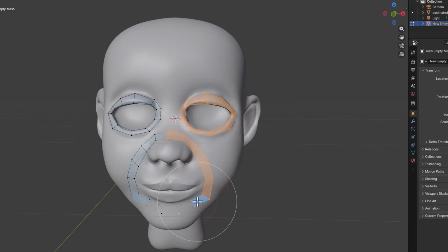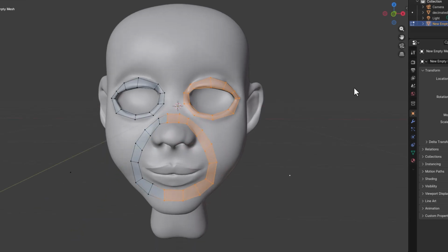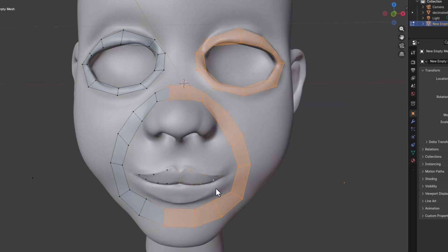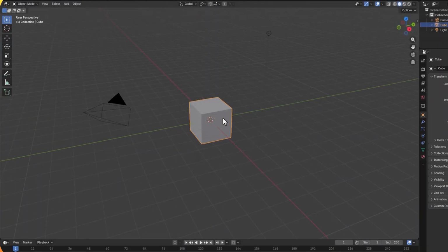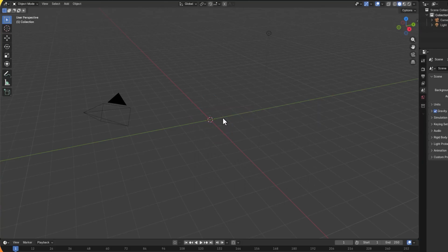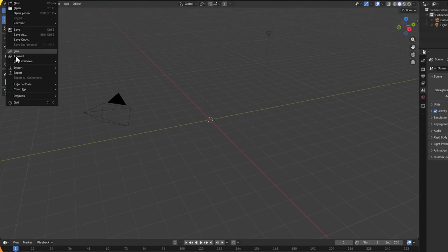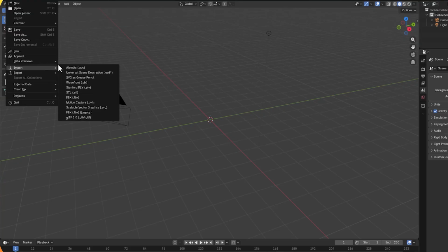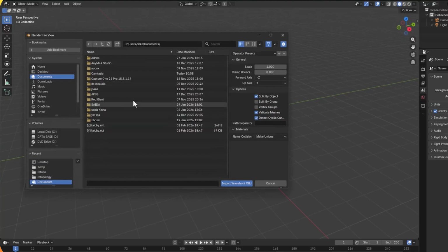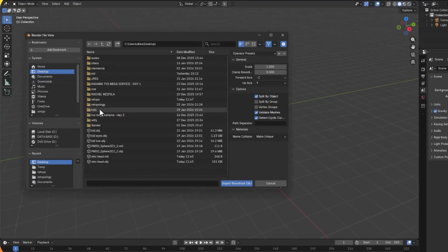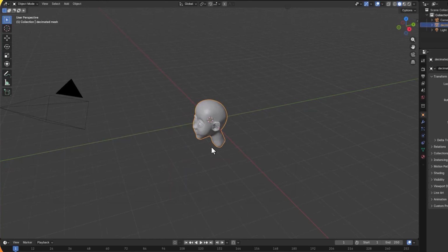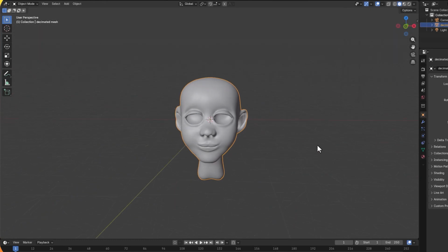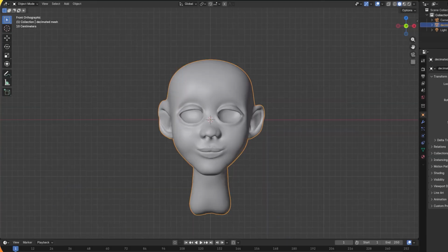In today's lesson, we will use another 3D software called Blender 3D to perform the retopology process. So let's get started and get to work. We open Blender. Let's clean the 3D workspace and import our exported mesh. We go to the OBJ file and go to the folder where we exported our decimated OBJ. So we go to Retopo and find the decimated mesh here. You see, that's where we landed from ZBrush.